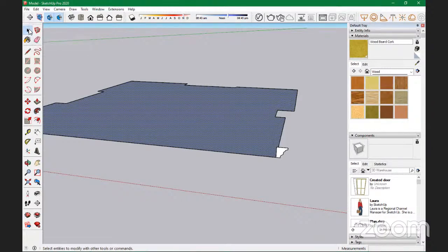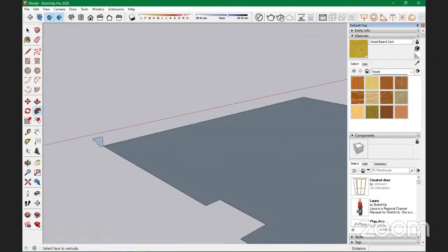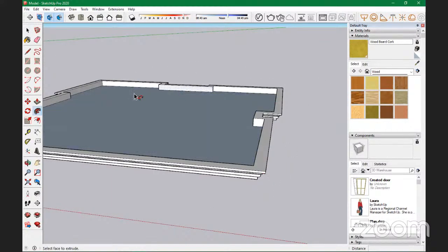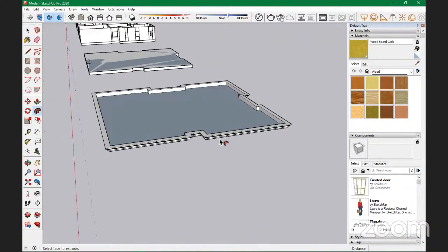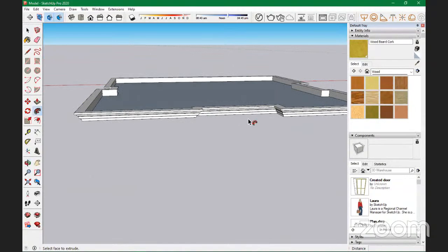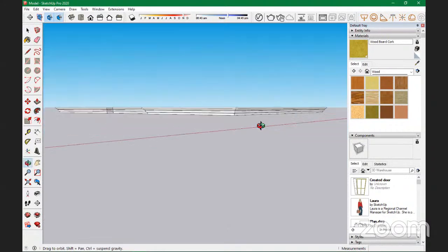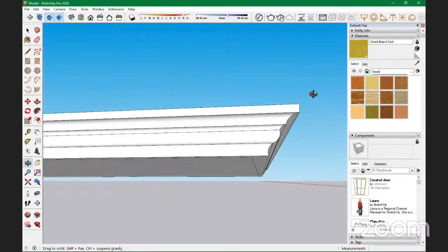Yes, it can be any design. So you select this, select your path. Then now you come select your follow me tool. After you select your follow me tool, you now go and look for the face. Remember, not the back. This is the back. But if you select the back, it means that it will be inside out. You'll be seeing this color all through. Of course, you can go around it, but it's always advisable to select the face. Now, you just select the face and it goes round that path, following all the curves like so. So you see, once you're satisfied with your shape, as you can see, we have our parapet looking nice.